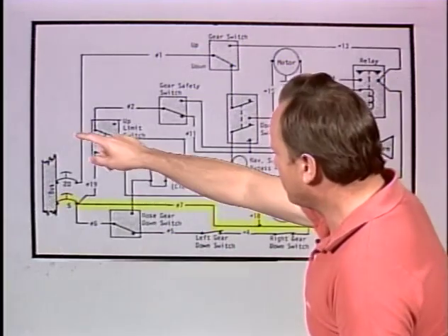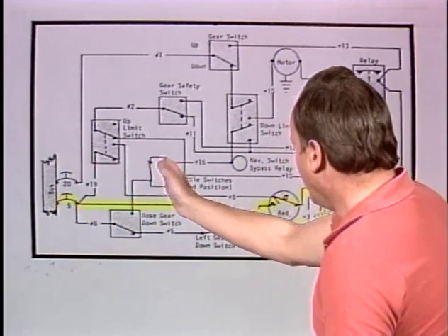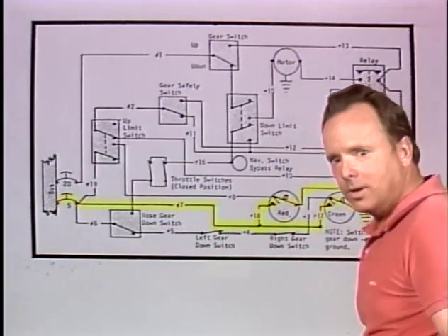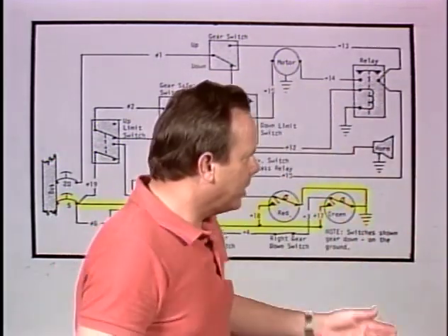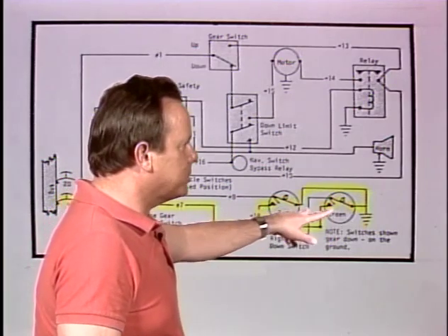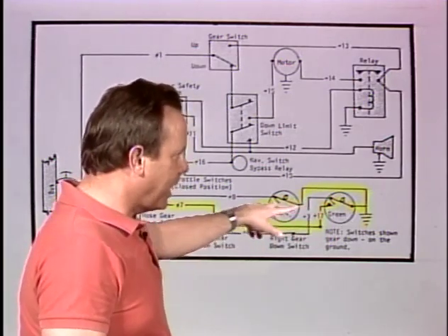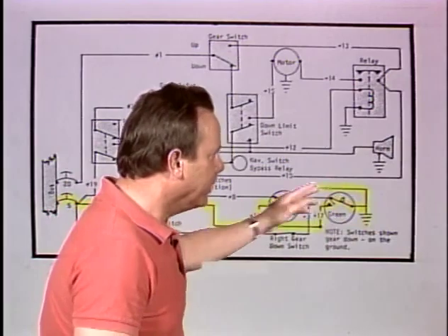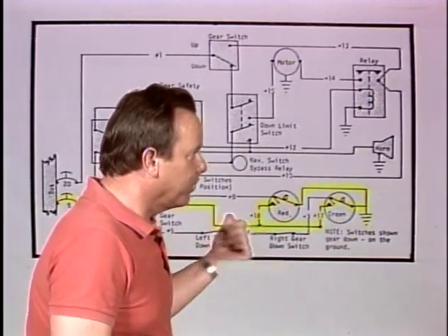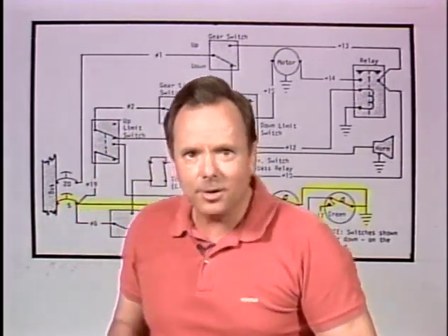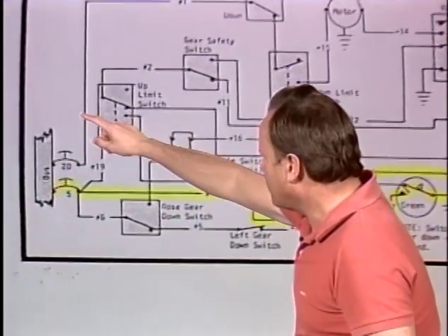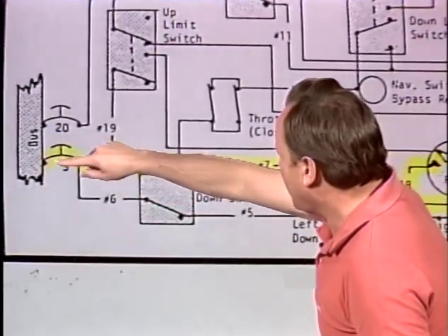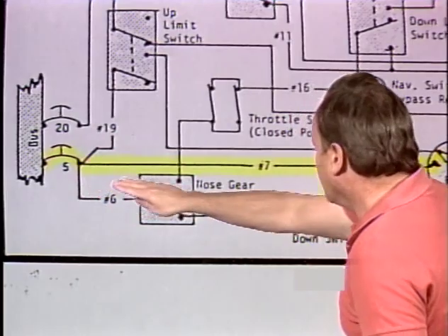First of all, we have the bus on the left-hand side. Wire 7 will go around here. We'll trace this in more detail in just a second. And then you get over here on the right-hand side, a couple push-to-test switches and lights, and then finally a ground. So what we need to do is complete the circuit from the power source to the ground. All right, let's start over at the power source. And here we have a bus with a 5-amp circuit breaker, and then wire 7.